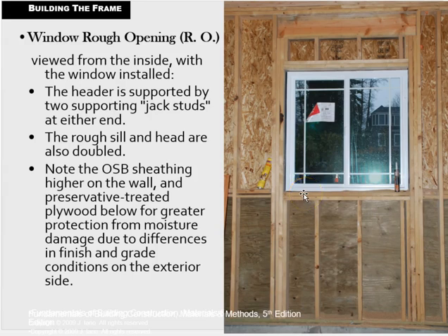So this image is a little kind of peculiar. I've never actually seen this one. This is where the header here has been pushed up to the top plate, actually, and the cripples are below it. Typically that would be mirrored. I'm used to seeing the header, and these 2 boards put in here. So this is a little wasteful. These 2 boards don't really need to be here at all. If the header were down at that location and the cripples above it, yeah, I'm not sure what exactly you're buying with this, in terms of what the benefit of that is.